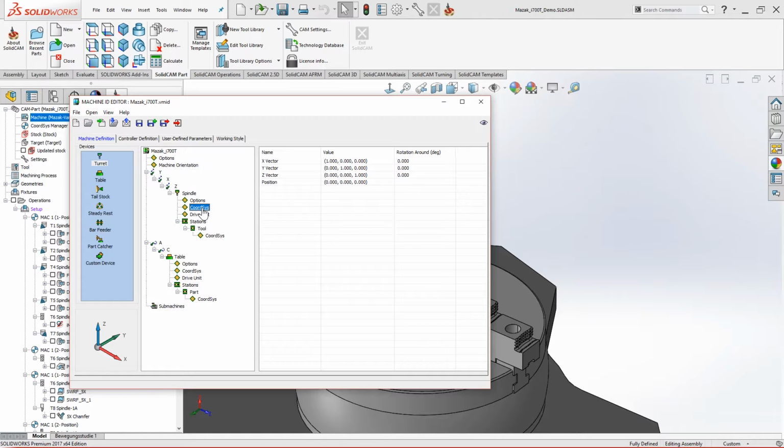of the next videos. In this case, I'll just leave it as 0, and as well on the tool itself it will be 0. So far I'll just change the coordinate system of the table. Now I can leave the coordinate system to be 0, 0 and just remove our part position, or I can just change the table coordinate system over here and leave the part station to be 0. So it's up to you.